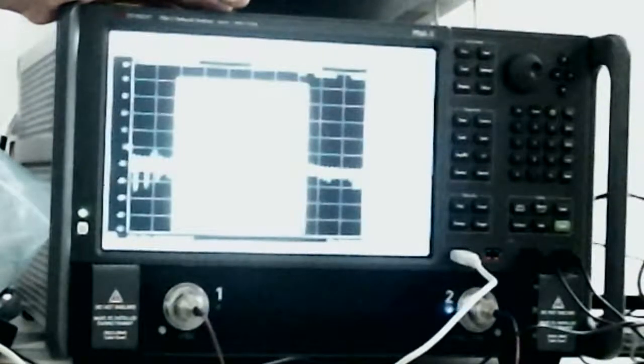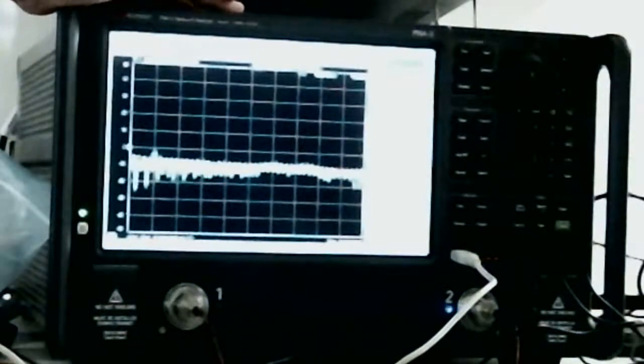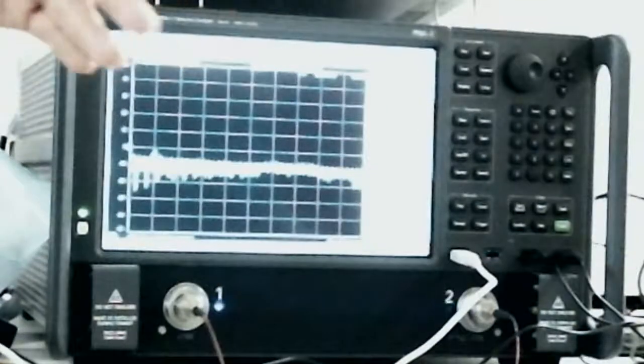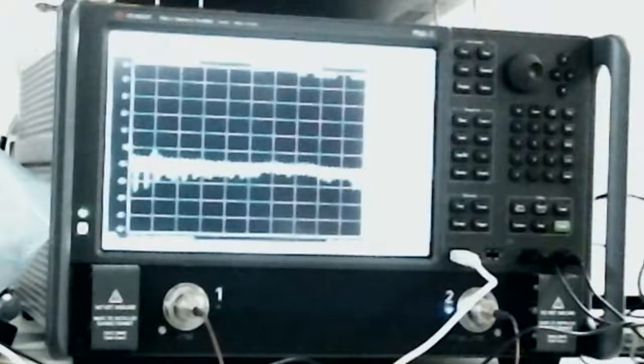Then can you sweep power? Absolutely. For example, to get the intermodulation or P1 dB compression, yes, to some extent. So this will give you the gain curve, and then you can look at the data and post-process it to get P1 dB, or put a marker and say find the delta to this marker to 1 dB. So there's some ways you can do that.